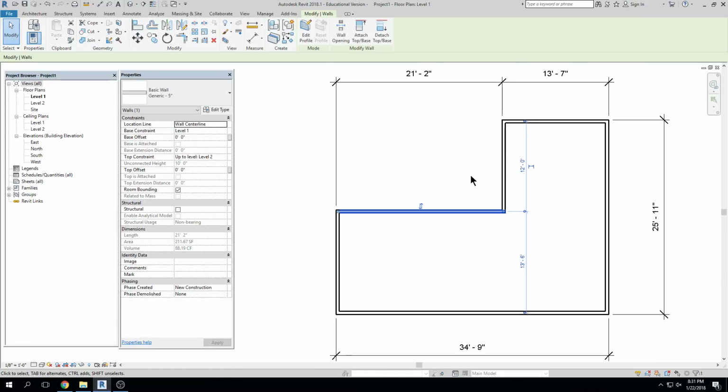In a very simple drawing like this, you're not really going to mess everything up, right? But when you get a lot of stuff in this drawing, you may be selecting this wall, but maybe you don't realize you've selected a floor below it, or you've selected something else by accident. And so dragging is risky. It's a very risky move because you might be grabbing something else that you didn't mean to, and it will throw everything else off, right?